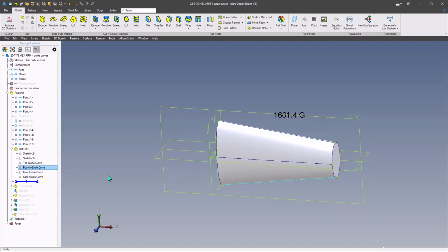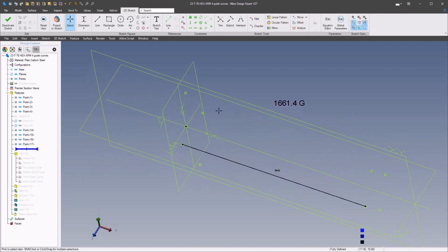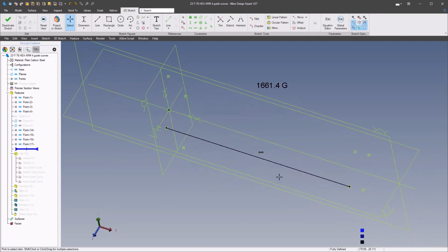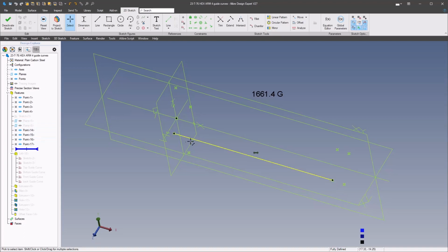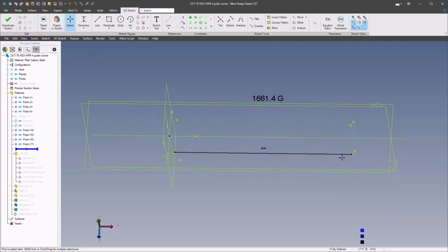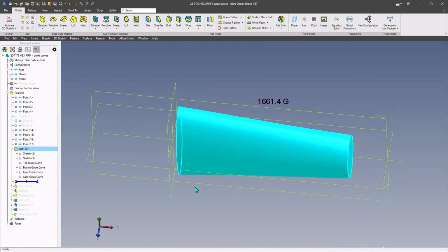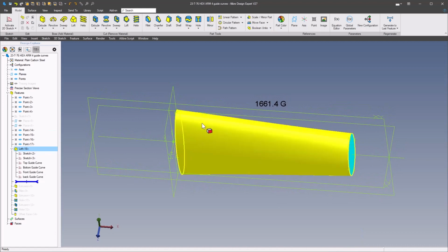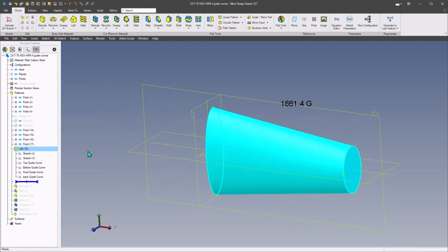And I did that for each top and bottom guide curve. And then on the front guide curves, I actually went in and I added more reference points on the reference planes, or the new planes that I created up here, and then constrained. Basically, they end up being a horizontal line to go between each end of the loft, because the loft is going to maintain its constant thickness across the minor diameter of the ellipse.